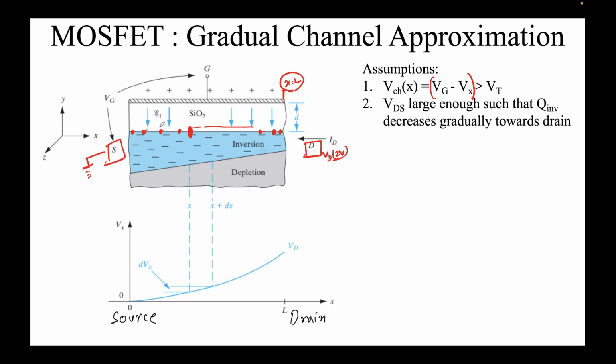Now just look at the extreme left and extreme right. On the extreme left, the potential you are applying is Vg, and that Vg has to drop in the oxide. Recall the expression: all the gate potential that you apply has to first go into making the bands flat, second into the depletion, then the band bending, and then the inversion charge. So there are 5 components. If Vs is equal to 0, the potential at this terminal is 0, so more of it will go towards the inversion.